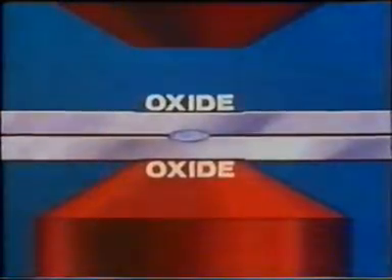A small weld nugget lacks strength and can be caused by too short a weld time, incorrect pressure, or an oxide film on the surfaces which can hinder the current flow. A small nugget can also be caused by the close proximity of a previous weld, which causes shunting. Most of the current chooses the easiest path and bypasses high resistance at the junction. An oversized weld nugget also lacks strength and can be caused by too much current, too much time, or too little pressure, which allows the molten metal to exude, resulting in a splash weld with cavities in the nugget and possible separation of the sheets.